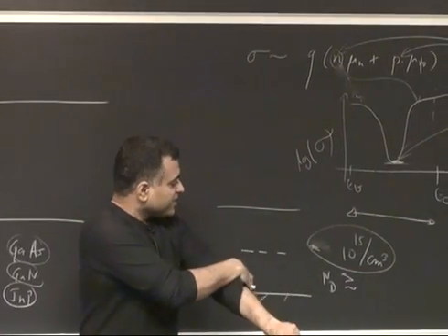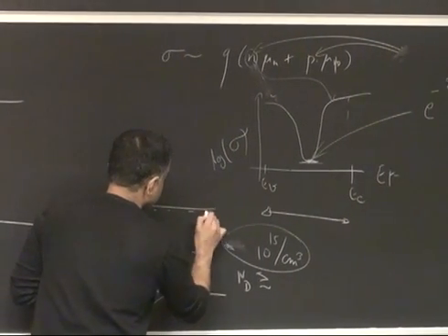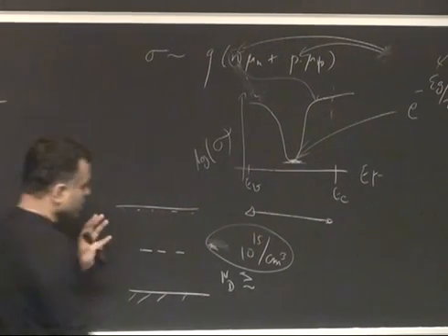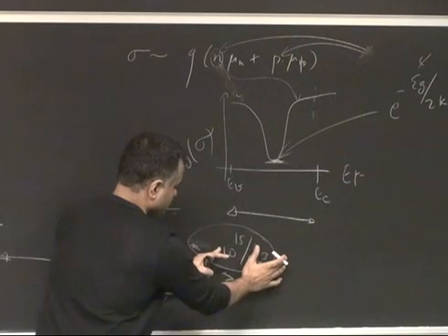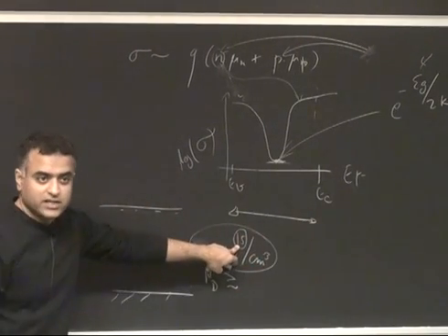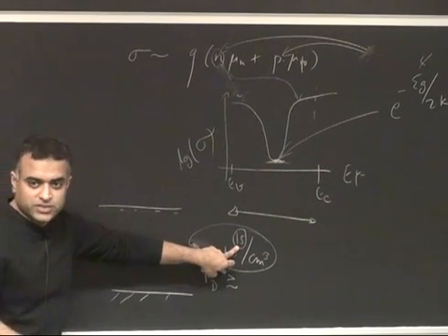Okay. So what does that mean? Because of unintentional dopants that have gone in, either due to statistical unavailability or during the growth, they've gone into the crystal. So out of 10^23 per cm^3 gallium and nitrogen atoms, 1 out of 10^7 atoms is an oxygen, for example. Cannot avoid that, right? And that's a dopant, right?